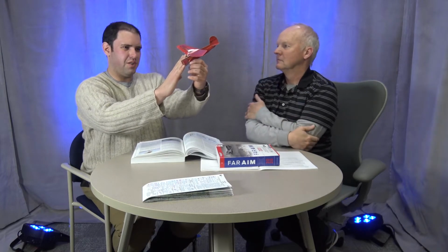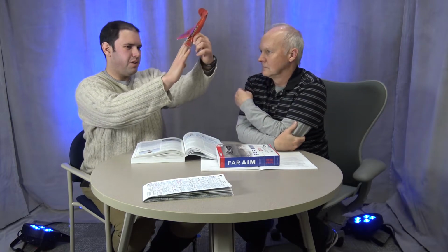We've talked a little bit about the airplane pitching up in terms of increasing the angle of attack. Although it might be said that the angle of attack doesn't necessarily have to do with the angle that the airplane is relative to the horizon. For example, if we take this airplane and head it straight down, and we try to change direction, so if we pull up, the airplane is trying to change direction. If you try to change direction too quickly, even if you're going down, the harder you try to change direction, the more angle of attack you get on that wing.